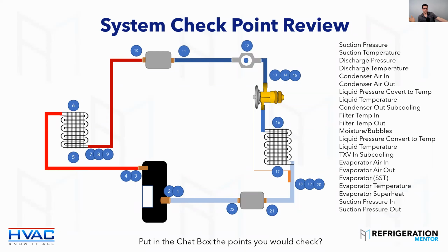Burnout. Okay, yeah, you have a bad burnout, electrical failure. You got to figure out why that happened. Most technicians don't know why. I didn't know why. I usually say it's electrical failure, the burnout, but there's always a reason why. There's a compressor issue or mechanical failure that causes that issue. But do you change this filter dryer? And when do you change this?